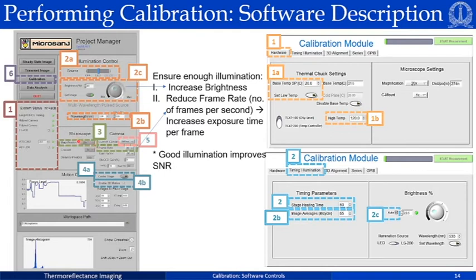Okay, now the moment you put your device, you also have to choose the microscope objective depending on the features in your device. If your device lengths are very small and you have very fine features and you want to have nanometer, submicron regime mapping done, you have to obviously use objectives with higher magnification. Okay, with these numbers set, we go to the piezoelectric control. You see the piezoelectric control parameters are set here. You have to click on center stage. That will ensure that the XYZ values, that the piezo stage, is at the center, and you have to enable 3D motion so that it can have live feedback of the positional shifts during measurement, and it can therefore correct those shifts.